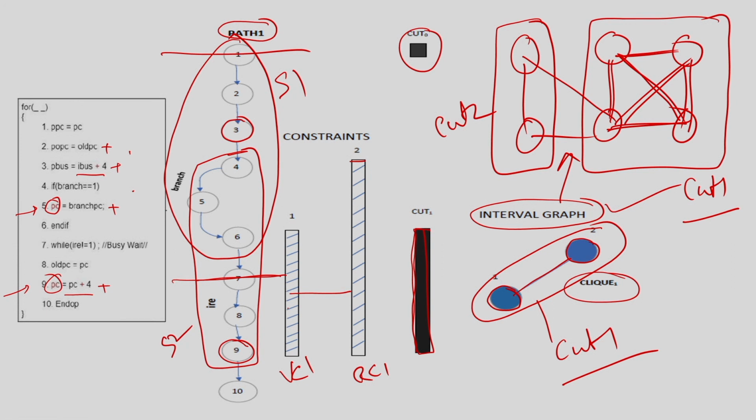Okay. If you ask me how to do it automatically, I am going to construct an interval graph from these constraints where each node represents one constraint, and if 2 constraints overlap, I add an edge. Once I have that, I want to identify the maximum subgraph which is a complete graph, meaning there is an edge between all of them.